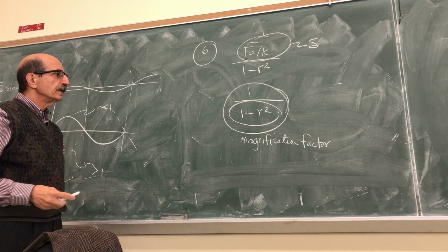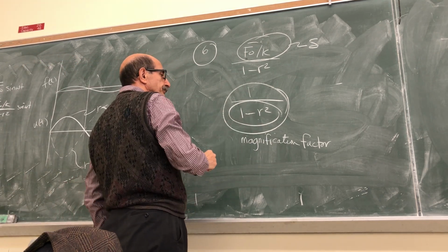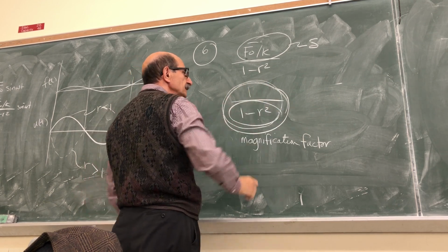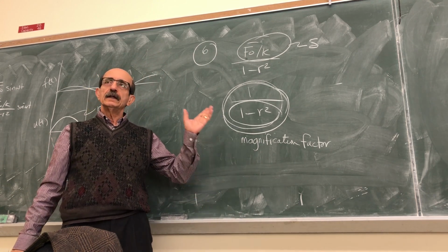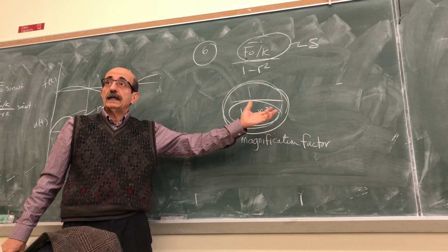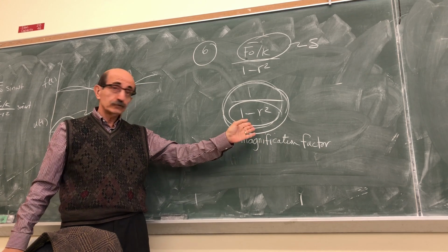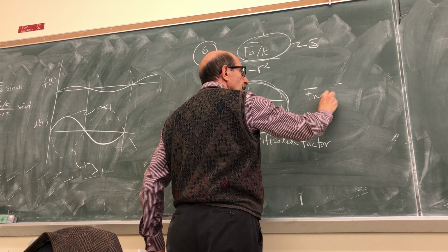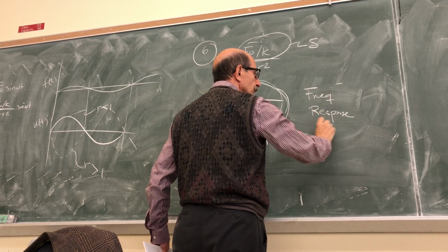in general, since this is frequency dependent. It is this function that really tells us what happens to a system under a harmonic load as compared with a static load, and it is a function of frequency. We also call this the frequency response function.